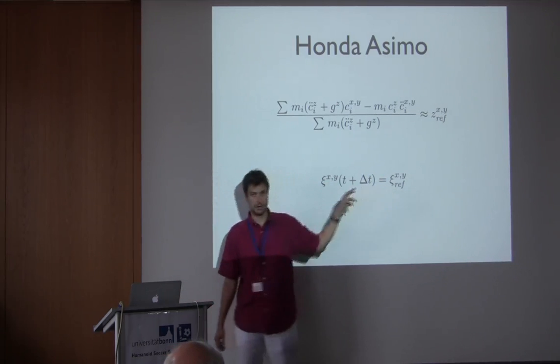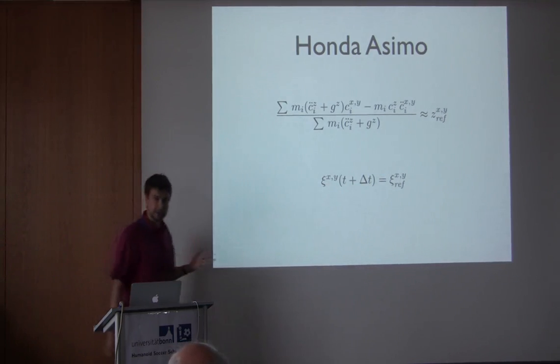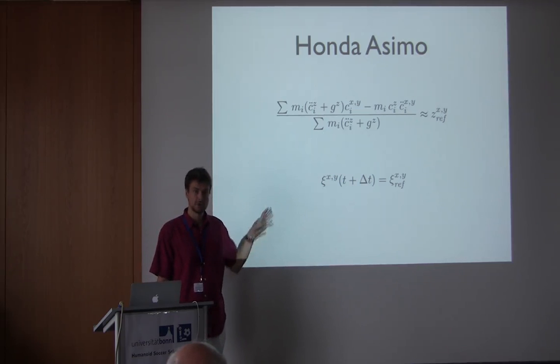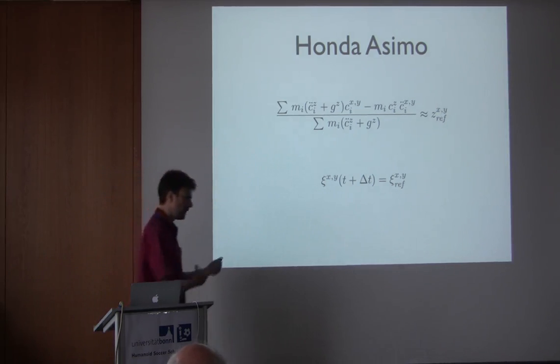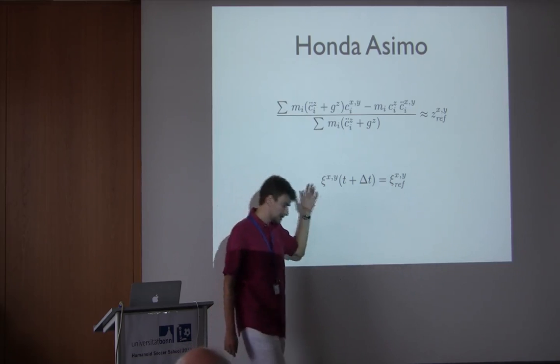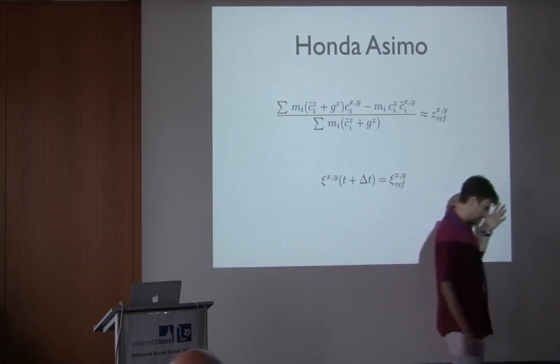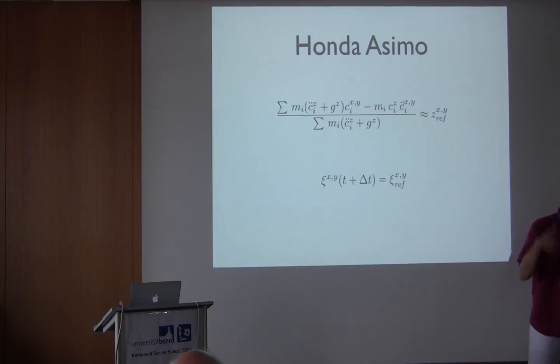How is this reference computed? In fact, they compute it so that they have a constant speed. If you look at the paper by Takenaka in IROS 2009, I think, you have the reference in the paper. Basically, they impose this goal. They say, well, I don't want to stop in 2 steps, I want to be in a cycle in 2 steps, because I know that this is viable. It's not capturable, it's viable. And they then decide where to put the reference by some general rules and solving equations.